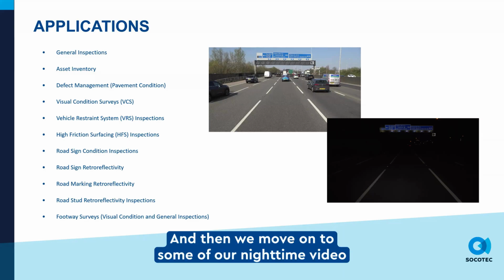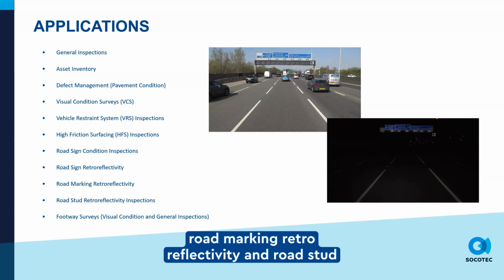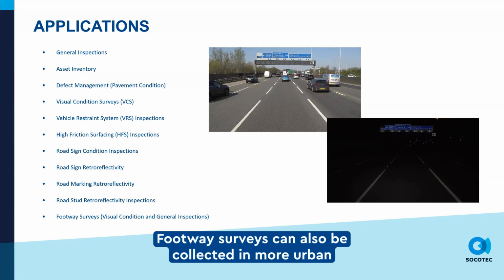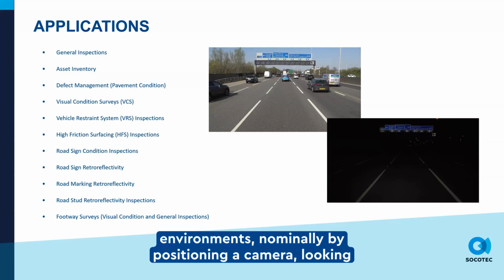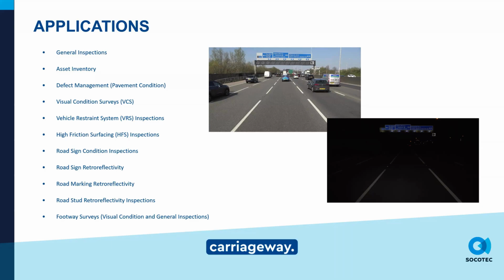And then we move on to some of our nighttime video data collection, looking at sign retroreflectivity, road marking retroreflectivity, and road stud retroreflectivity as well. Footway surveys can also be collected in more urban environments, nominally by positioning a camera looking down at the footway, recording the video from the carriageway.